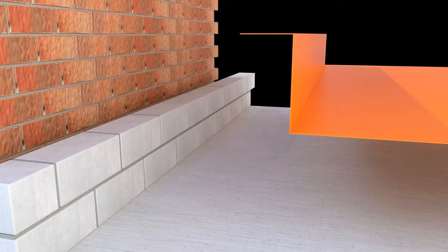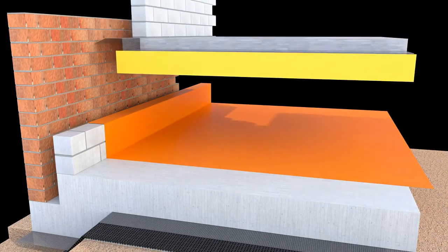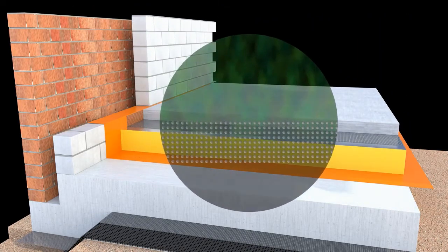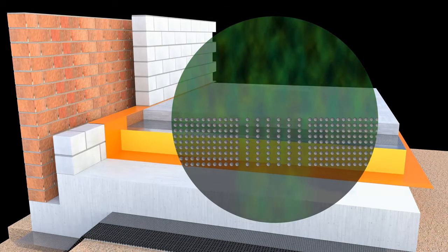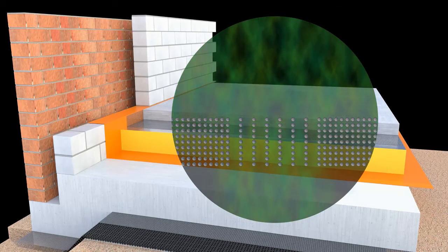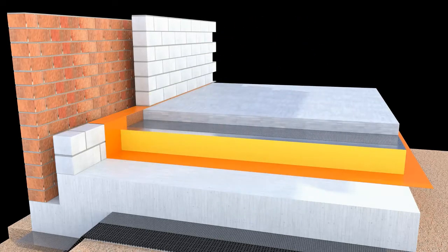Studies suggest this effect can be present at angles as low as 60 degrees for some membrane types. So at the 90-degree angles most commonly associated with foundations, it can have a significant detrimental effect on permeability performance. Secondly, if the membrane is not fully supported at these angles, the weight of any subsequent layers, such as the slab or screed, can elongate the membrane, reducing its thickness and increasing the permeability through the free space in the membrane as the molecular gaps are wider. Taken to an extreme, both of these scenarios could even result in the membrane cracking, splitting or tearing, and in a way which would not necessarily be obvious during a site inspection.